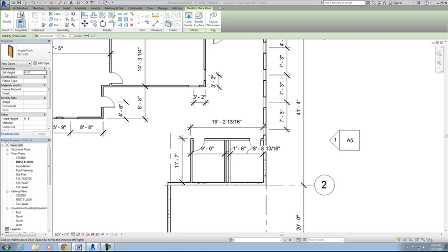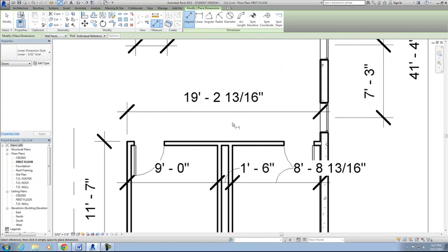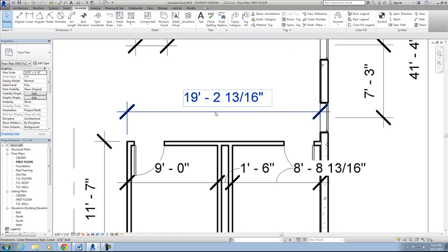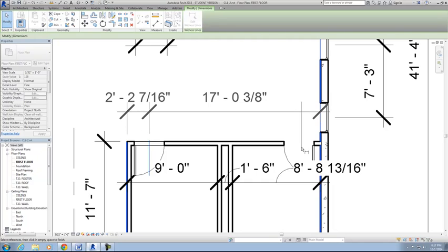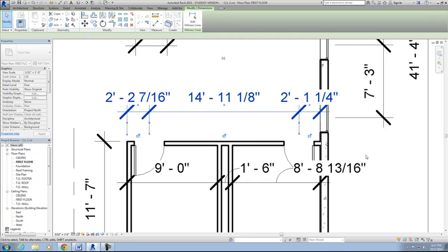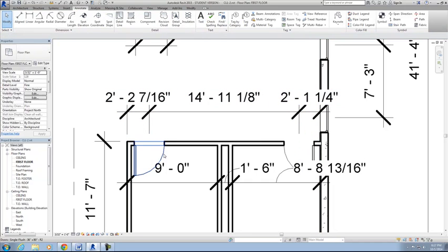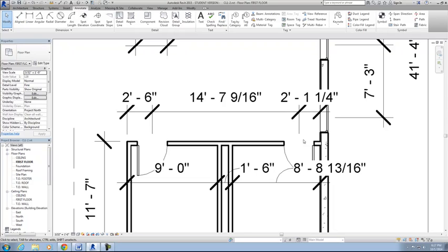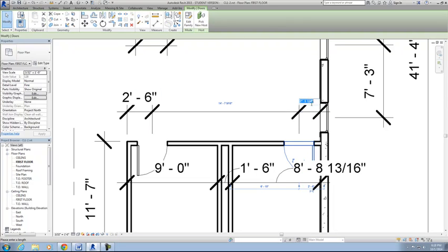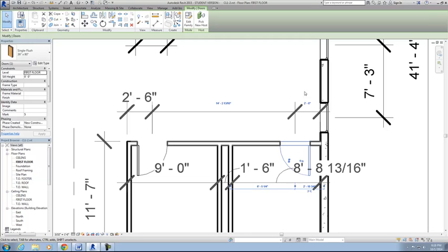Okay. Oh, actually it's on the next page. I should remember my own tutorial, huh? Okay, so let's go to Annotate, Aligned, and then we'll go ahead and use this dimension as our starting point, and then we'll add in the 2 door-centered dimensions. And then I just need to click on the door and modify the location to 2.6. Great.